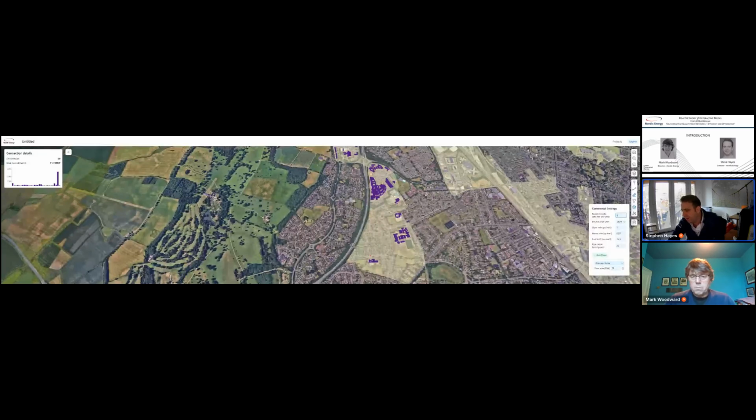I've pre-configured it to say that we're going to put in an 11 megawatt biomass boiler. There are different plant types and fuel types you can change here. You can do a bunch of sensitivity around those assumptions and parameters, and then you simply hit create heat network. Now what it does is it takes that location and all these different buildings, and works out a sensible way of how you would connect these to a district heating network.